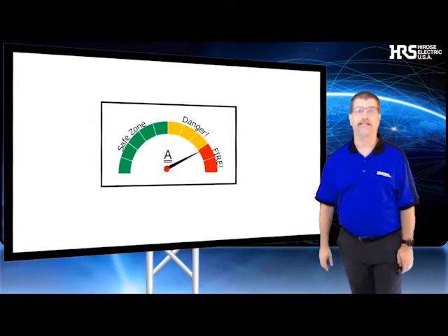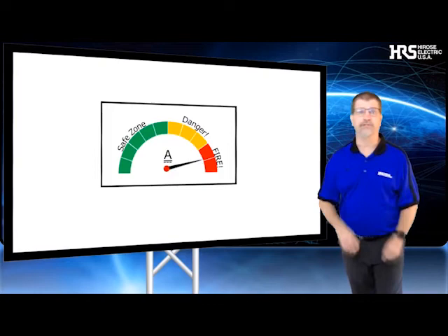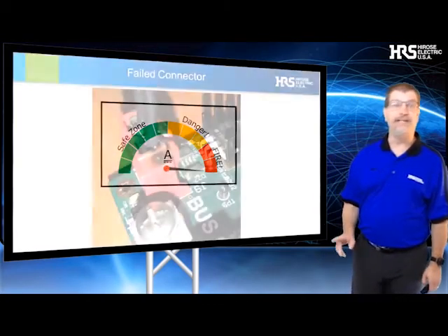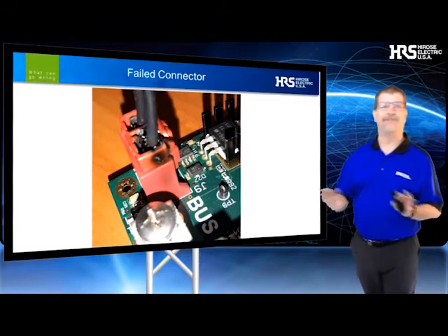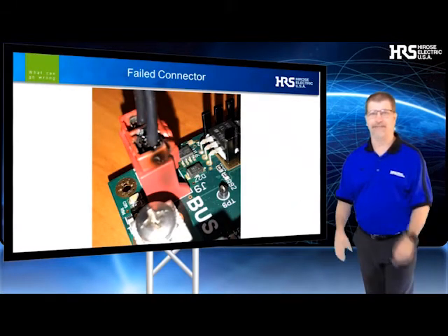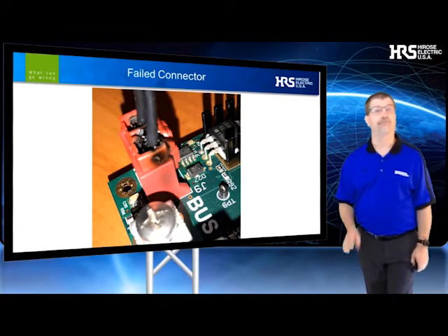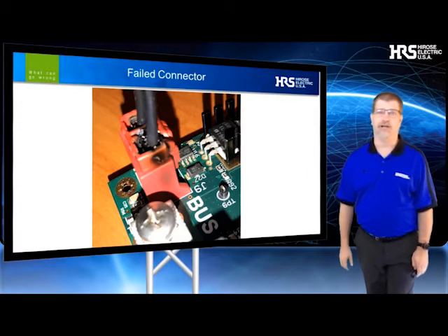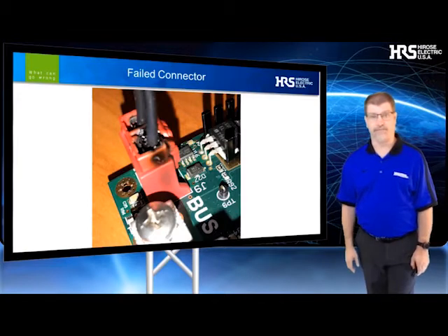As that contact heats up, yes, we know that will produce a higher resistance value. But the core problem still exists, and we need to be mindful of it. We never want an overheating contact. Connector and system failures become a real possibility in this situation. This brings us around to talking about the derating of connectors.